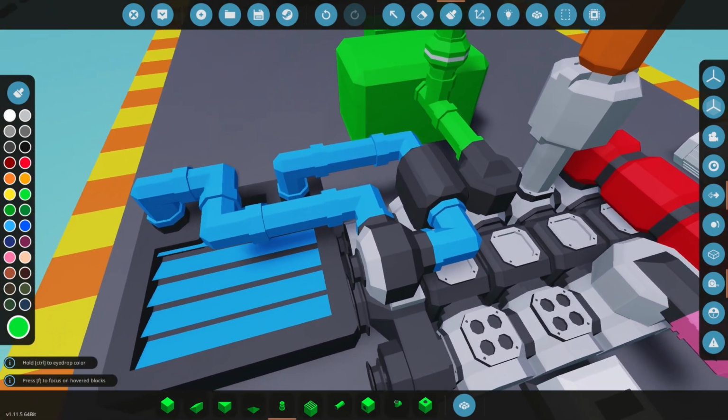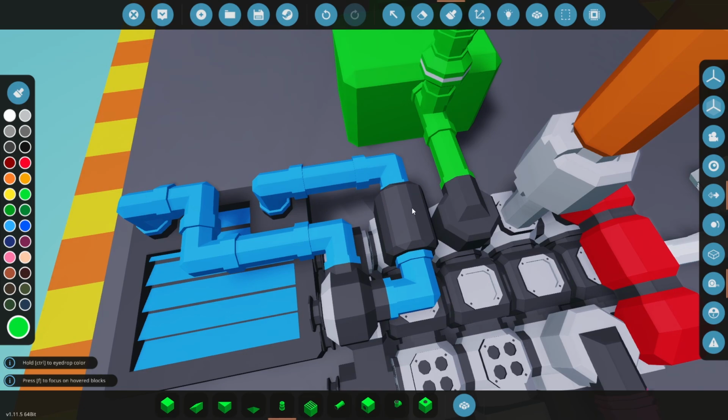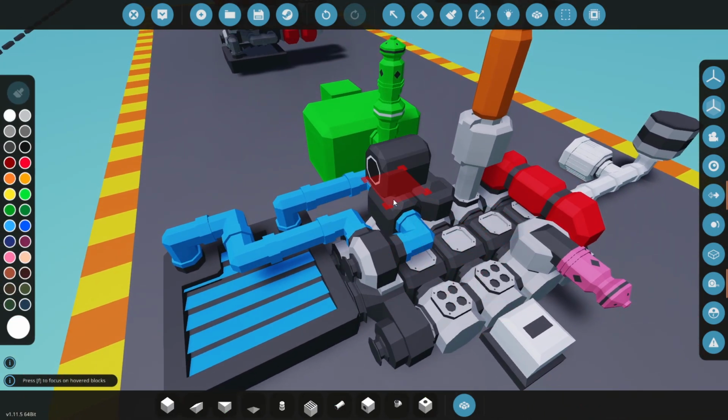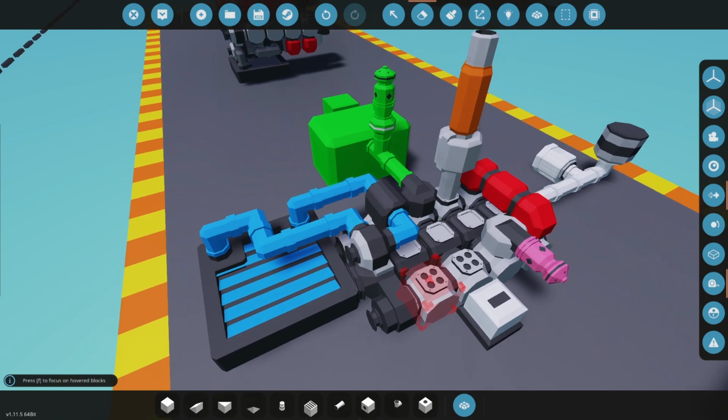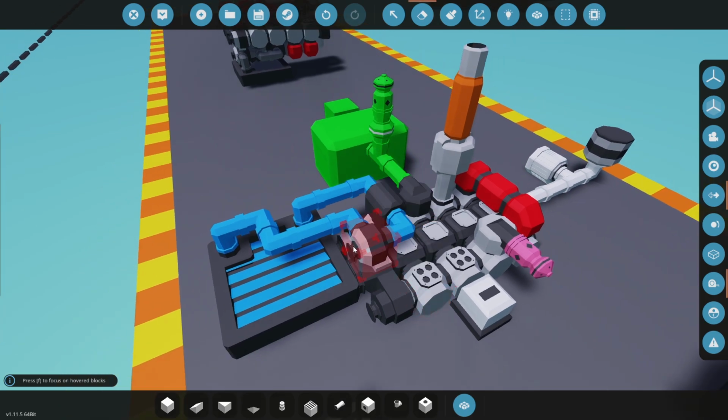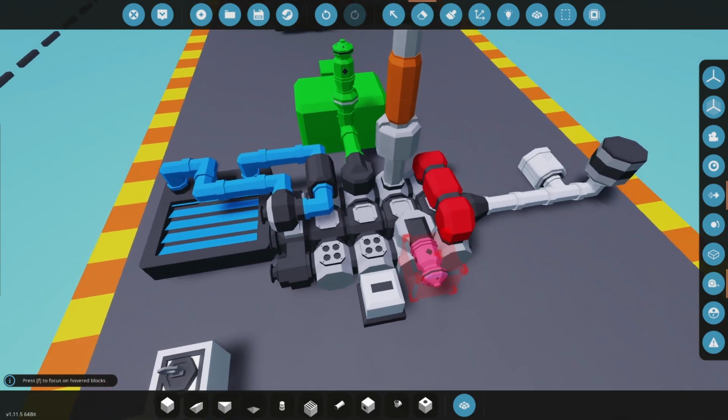As far as the cooling system goes, one common mistake I've made is missing the actual manifold, for example, or the pump, either or. You have to have the manifold attached to the cylinder, and you have to have a pump that's going to circulate coolant through the radiator system.